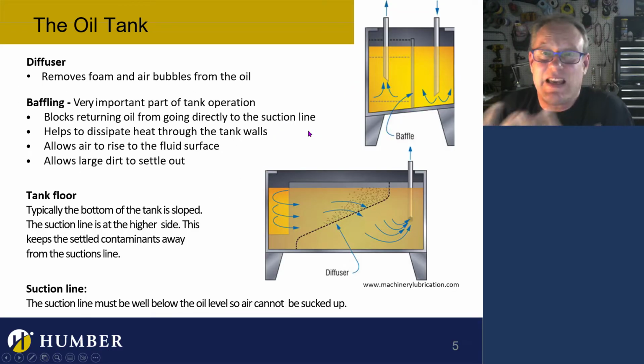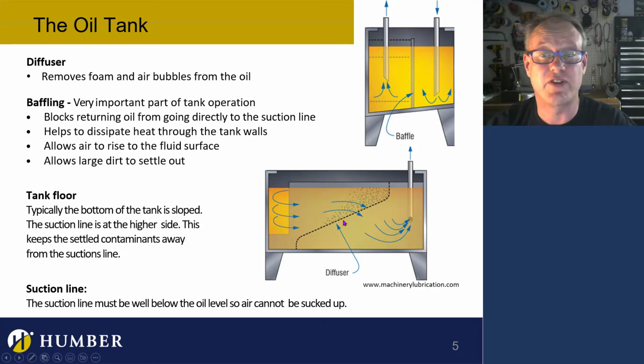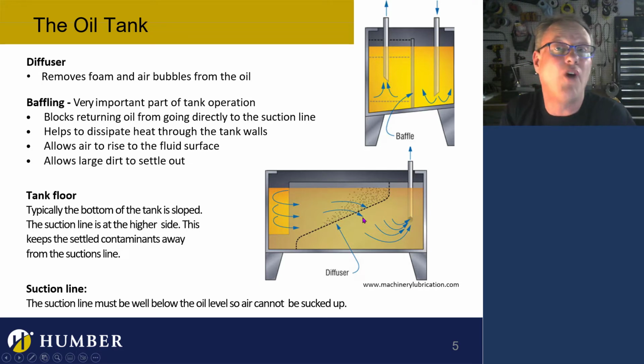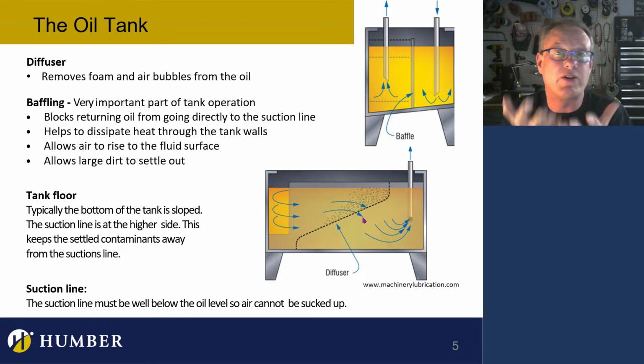This is the interior of the tank, what it actually looks like. A tank is going to have a sloped floor. It's going to have a baffle in it. I don't think there is a tank out there that doesn't have a baffle in it. Some tanks have diffusers, some don't. The diffuser is going to take the air or the foam, sometimes there's foam in the fluid as well, and it's going to allow it to diffuse up to the top.